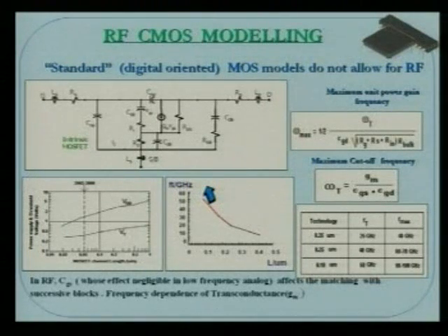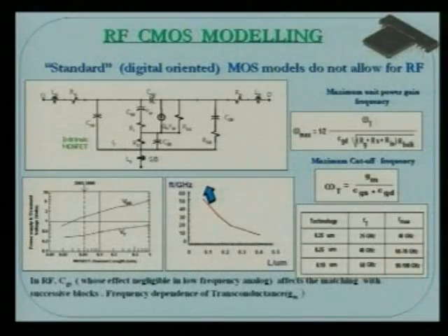For example, if you look at the 0.25 micron technology, the gap from source to drain, that length, is known as the technology. 0.25 is the length, where the threshold voltage is around 0.6 or 0.5, and the voltage level is 2.5 volt to 3 volt. But if you reduce that length to say 0.13 micron technology, then my threshold voltage goes down to say 0.4 volt, and my power supply VDD becomes 1.3.